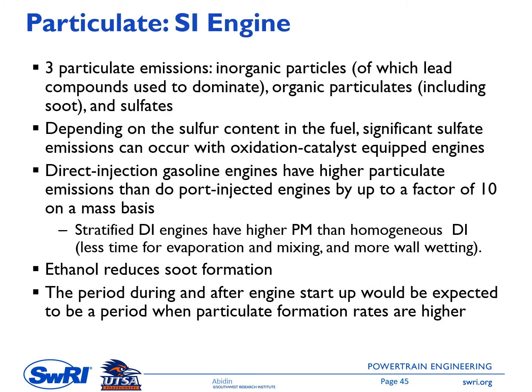For the spark ignition engine, the particulate emission consists of inorganic particles, of which lead compounds used to dominate, and then organic particulates, including soot, and the last one is sulfates. Depending on the sulfur content in the fuel, significant sulfate emissions can occur with oxidation catalyst equipped engines. As I mentioned in the previous slide, GDI has much higher particulate emission than PFI. It is by a factor of 10.